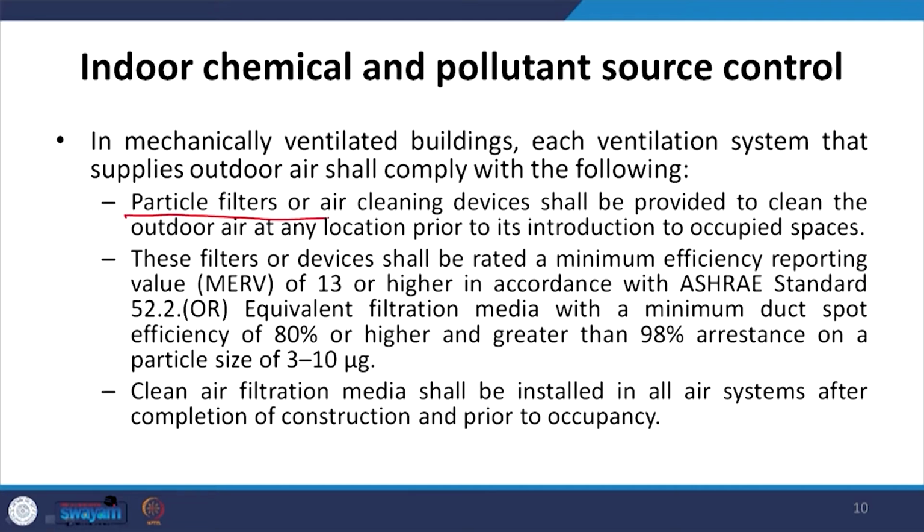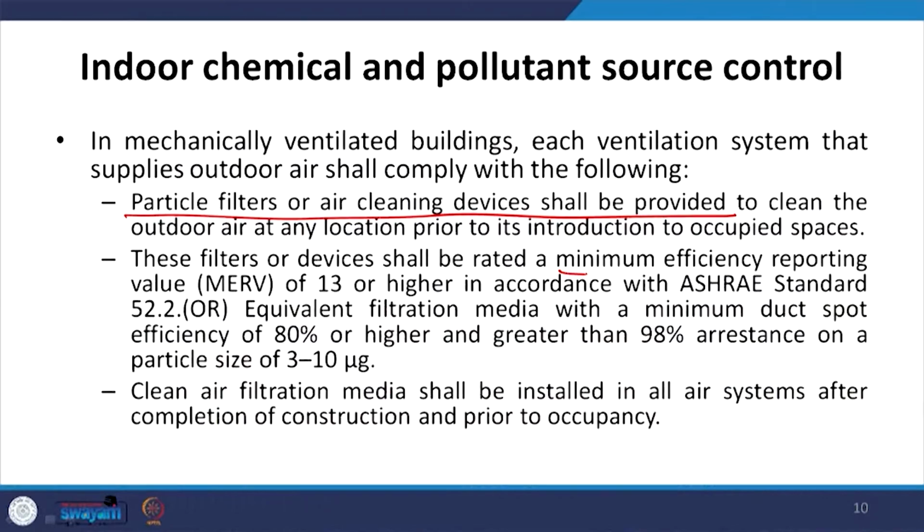First is particle filter or air cleaning device shall be provided to clean the outdoor air, and that is at any location before it is allowed inside the occupied spaces. So, it is not only for the hazardous chemicals or pollutants, but in general whenever the outdoor air is being brought inside, it should be properly cleaned and filtered. Also, the minimum efficiency which has to be reported, the MERV value as we say for these filters or devices, should be at least 13 or higher. This is in accordance with the ASHRAE standards, and it has to be maintained.